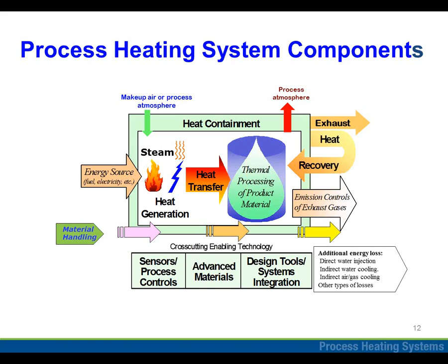And yet you have to deal with something else, which is, now you have the exhaust gases coming out. In some cases, we will have to recover the heat, as in reheat furnaces, we have recuperators there. And then in some cases, we'll have to put some sort of emission control system because there are restrictions on what you throw out in the air. And a prime example is what's going on in the arc furnaces, where we have a whole bunch of bag houses or electrostatic precipitators to get rid of the dust and so on and so forth.